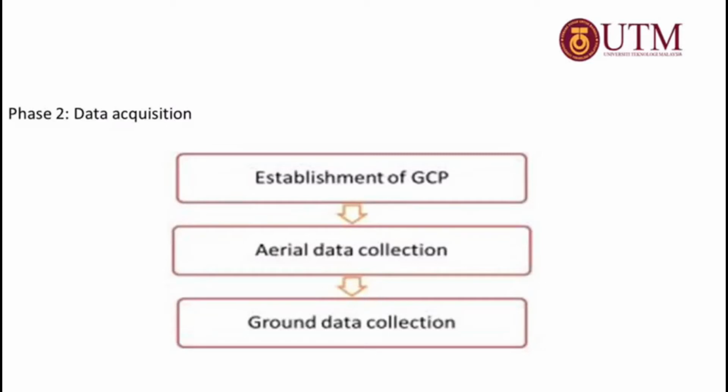In this process, UAV was flown over the study area to get theoretical view of the building and subsequently to obtain the images of rooftop for the study area. Few aerial photographs will be taken by the UAV that will further be used to generate orthophoto and point clouds. For aerial data acquisition process, a rotary UAV platform DJI Inspire 1 model was used for whole data acquisition to acquire image from the study area due to its ability and safety where the symmetrical position of the rotor helped the UAV to maintain its planar angle.